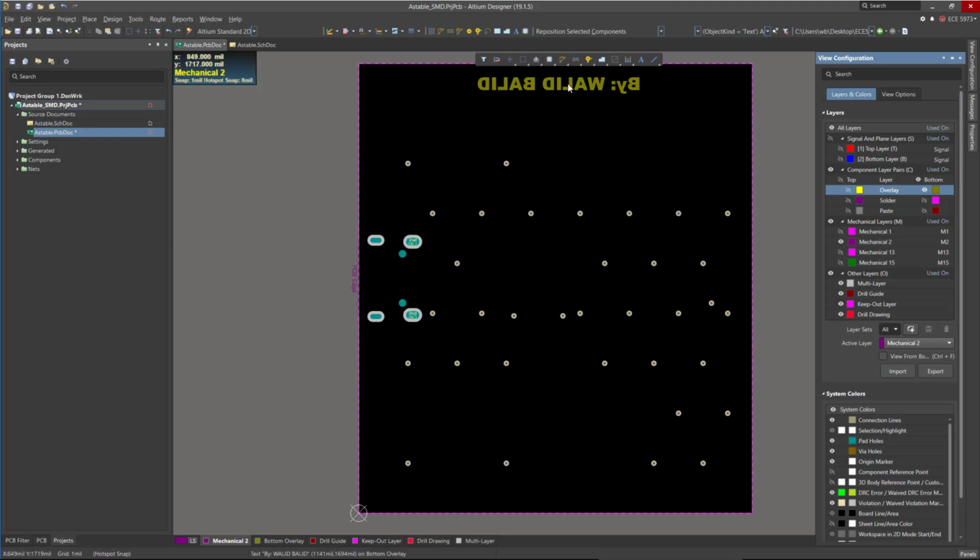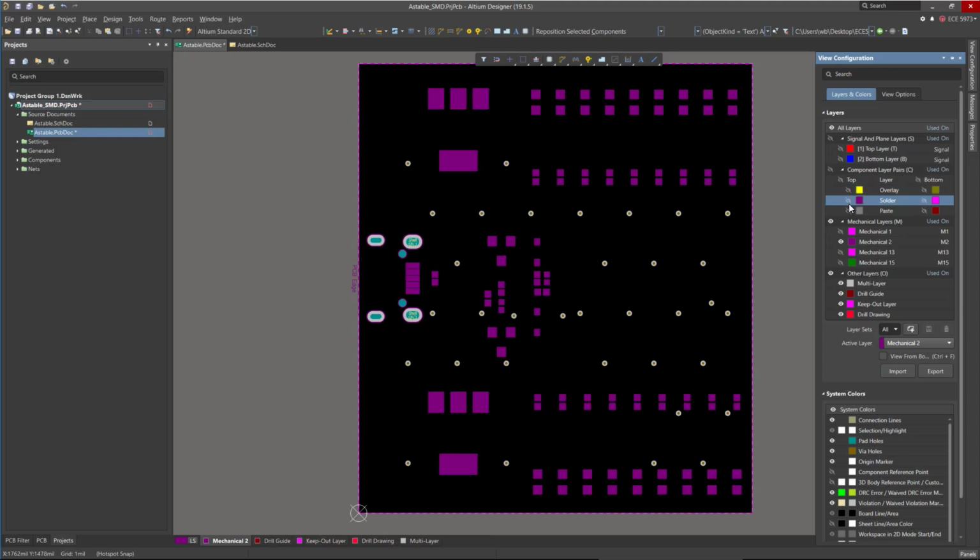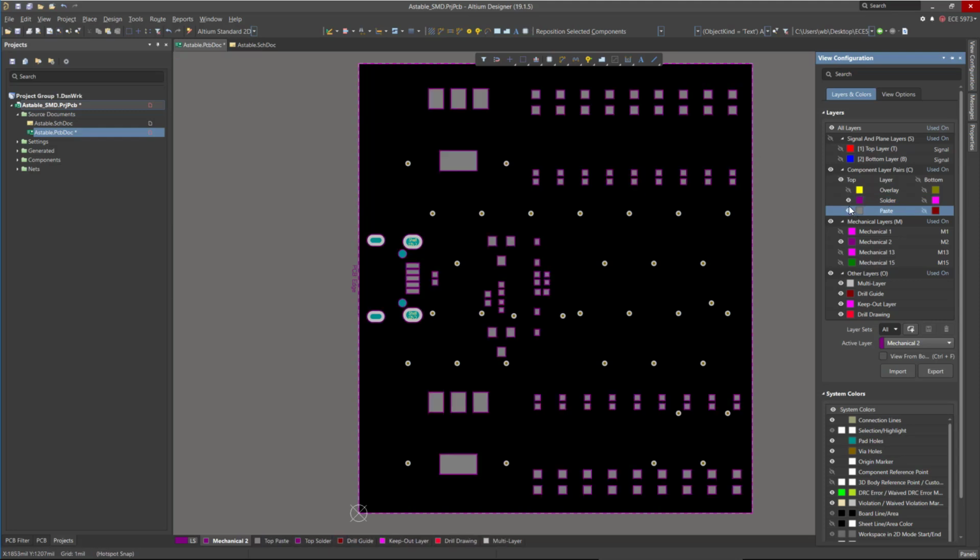If you really don't need it, it's better not to have it because you will save cost. If you don't have silkscreen on both layers, this is cost saving. So basically this is solder mask. This is the solder paste location, and yeah, this is the solder pads and this is the solder paste. So when you do a stencil printer, they count on the solder paste layer to laser cut the stencil.